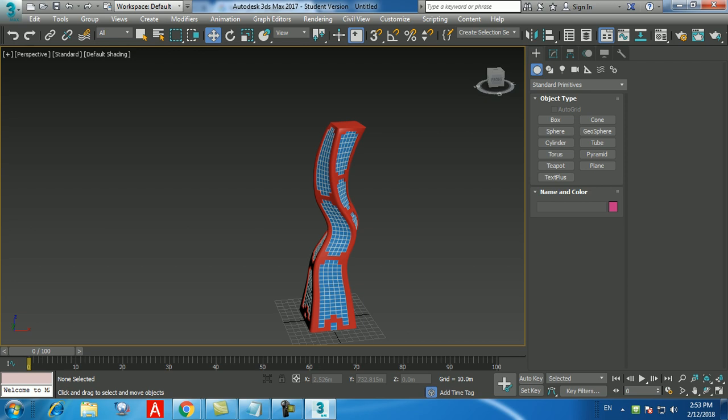See, in AutoCAD, if you want to change a plan, you will change it. But for the elevation, again, you need to go to the elevation and change it. In Revit, it will automatically change. For example, in AutoCAD, let's say you want the dimension to be 2000 millimeters, but it's 2100. You can double click on the dimension and change it. In Revit, you cannot.